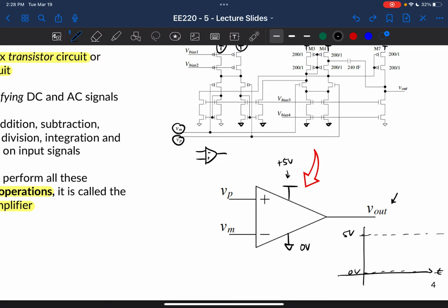I can't put an input of 2 volts in with a gain of 10 and expect to get 20 volts out, because it just can't happen.